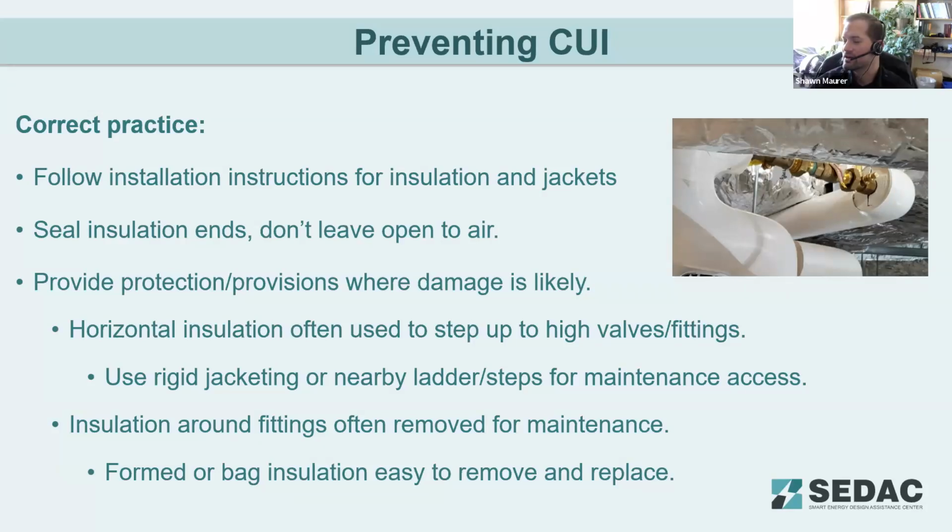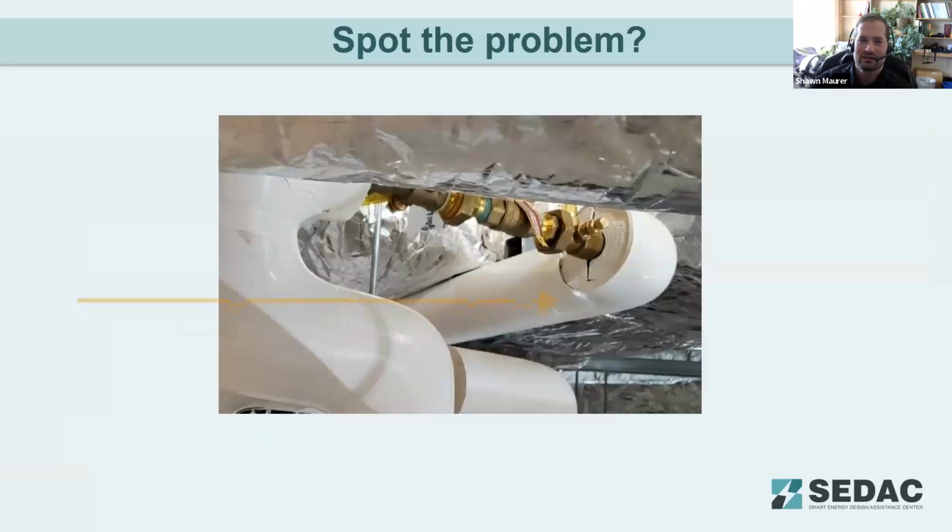And just a quick note here, in the example image, you can see there's a little bit of an error. We're going to point that out for you. There's a little bit of air gap where this end cap hasn't been sealed properly, or the sealant was applied, but there's a crack in that insulation. If this was chilled water piping, this would be a concern for corroding that piping and getting moisture in that insulation. As this is hot water, it's not as much of a concern, but still something to be aware of in practice, particularly on these ends, to make sure that they're sealed up properly.